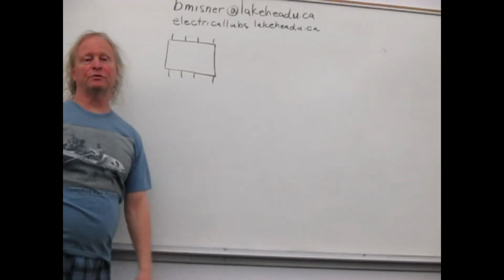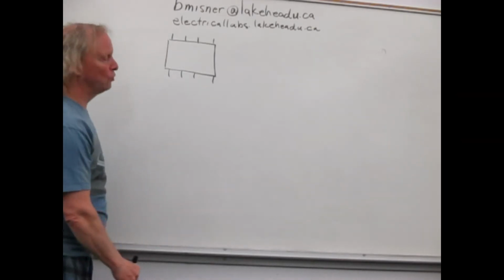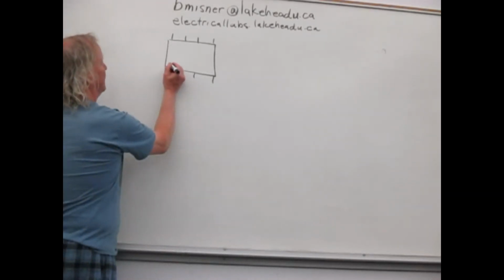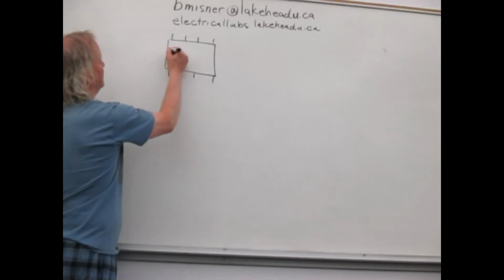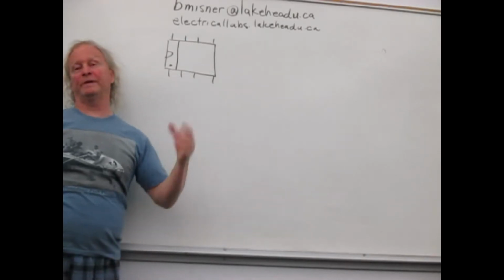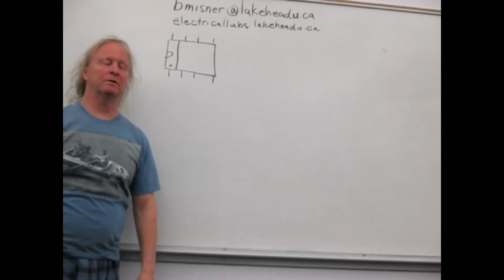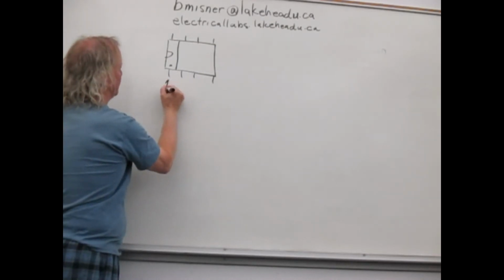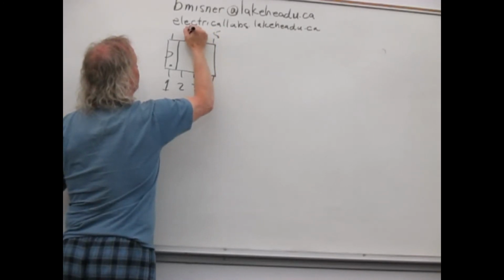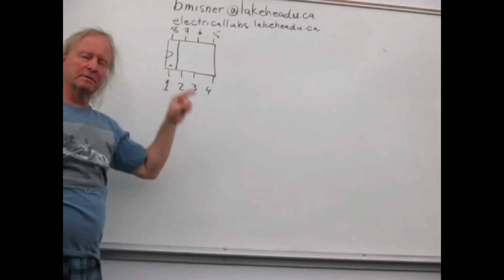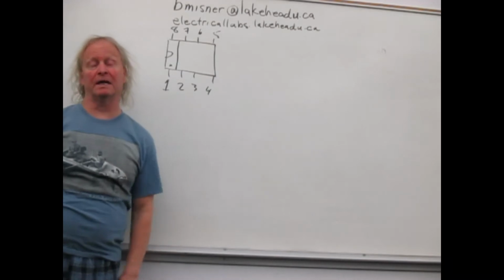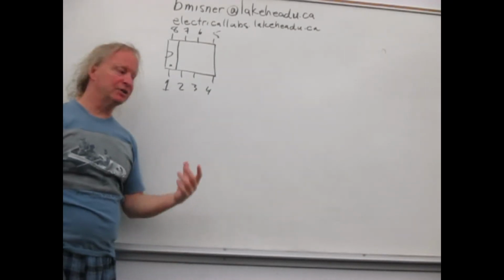The very first thing you want to do is find out which is pin number 1. Normally there's different denotations depending on the manufacturer. It could be a dot like this. It could have a little cup, or it could have a bar, or it could be a combination of any of the above. Okay? And that says that this is pin number 1, 2, 3, 4, 5, 6, 7, and 8. It numbers it around in a horseshoe. And then usually it shows you the connections to the device.